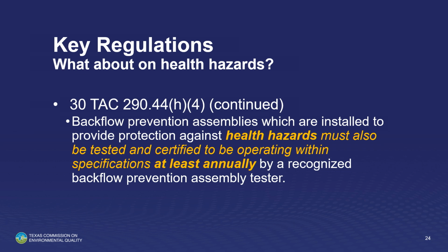So, key regulations. Backflow prevention assemblies, which are installed to provide protection against health hazards, must be tested and certified to be operating within specs at least annually. Now, that being said, if you're doing something else there, you can test it more than annually if you want, if you suspect it's not working. I don't know how many RPZs I've walked up to, and they're just gushing water everywhere. So, obviously, we have a problem. If you're a BPAT, it probably got a fouled number 1 check. So, but anyway,